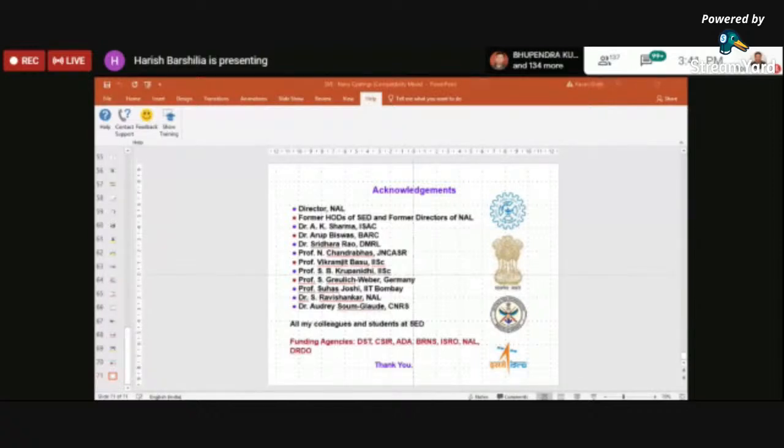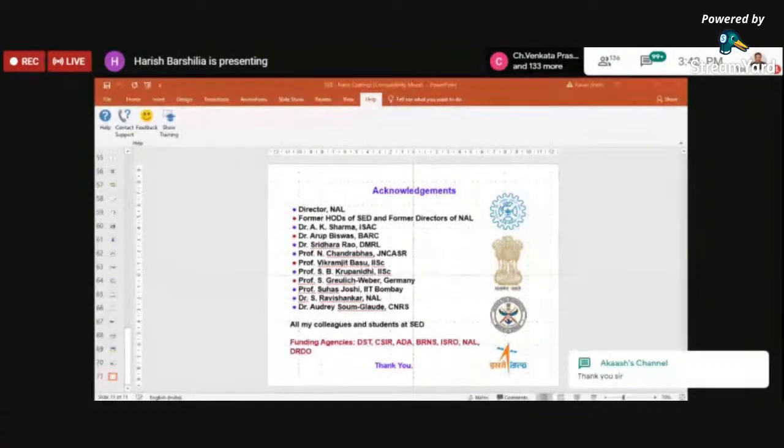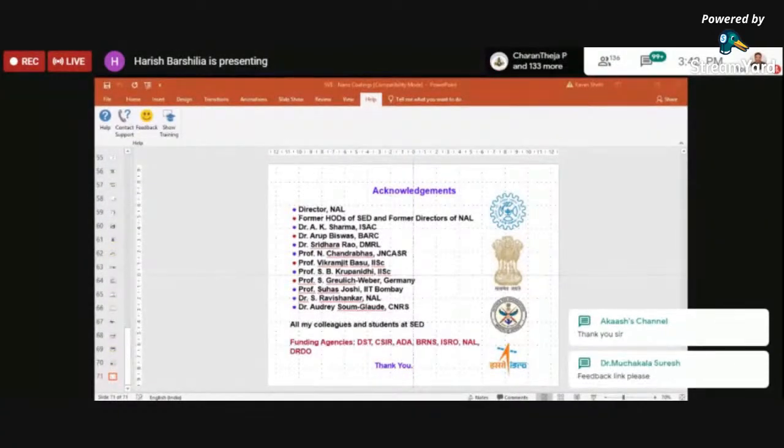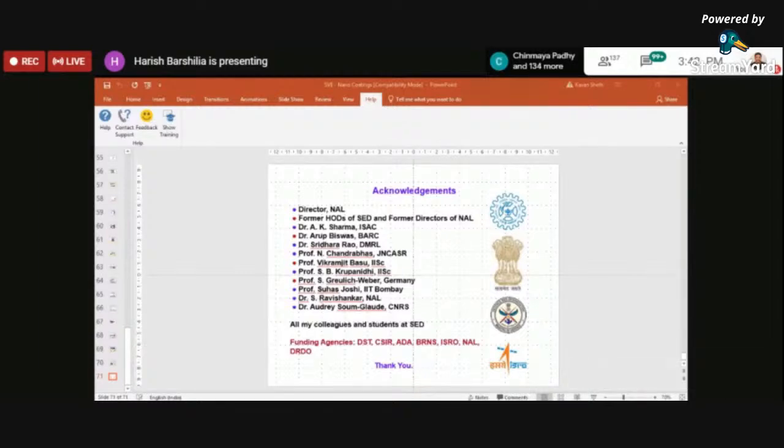At elevated temperature conditions, which one is more recommended, MoS2 or graphite coatings in an aluminum matrix? MoS2 is always preferable compared to graphite. The application is for piston rings, sir. Okay, in that case MoS2 will not work. You have to use graphite only, because in the piston some sort of moisture will be there, so MoS2 will form MoO3. This is not good, so for that you use graphite only, sir.